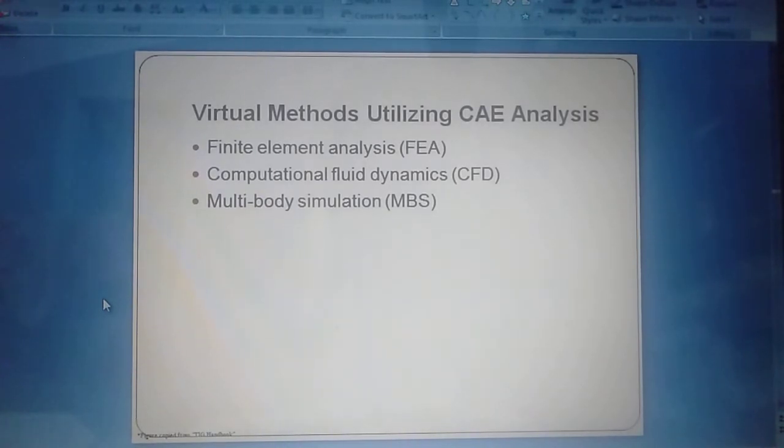The mathematical or geometrical model extracted from the 3D CAD model is discretized by the finite element method, resulting in corresponding numerical methods. Like that, the boundary conditions of loads, for example forces, moments, then restraints, bearings, fixed parts, material characteristics, temperature, and other factors are defined directly in the FEA program.